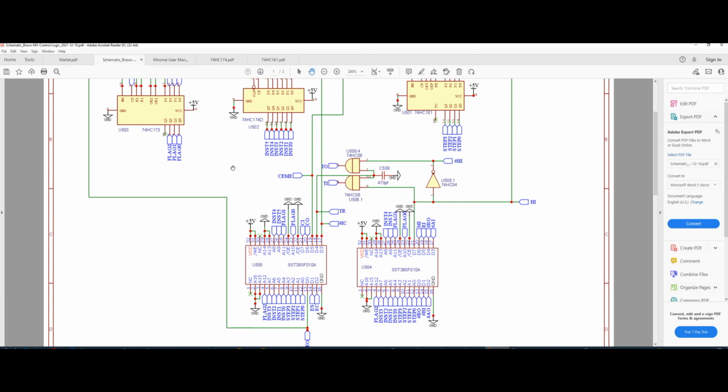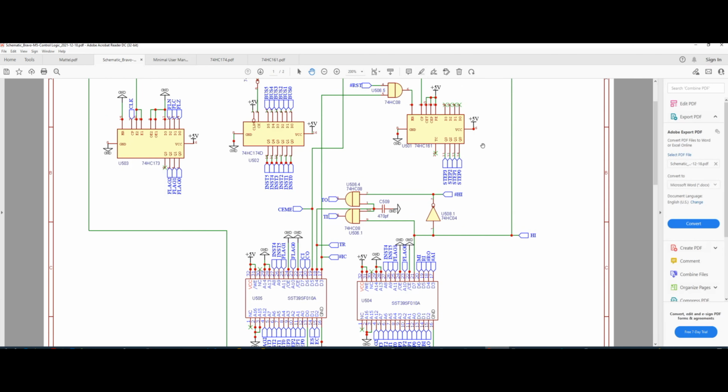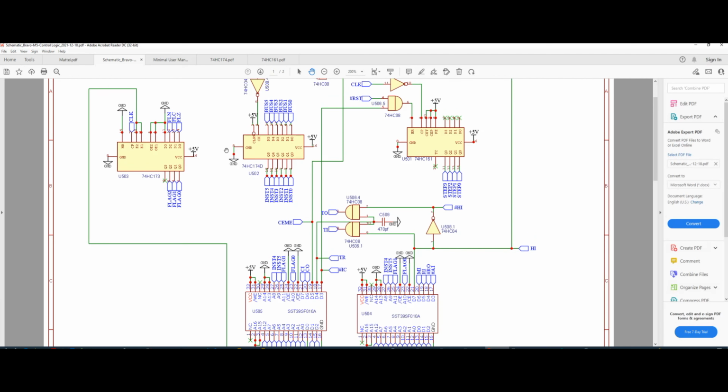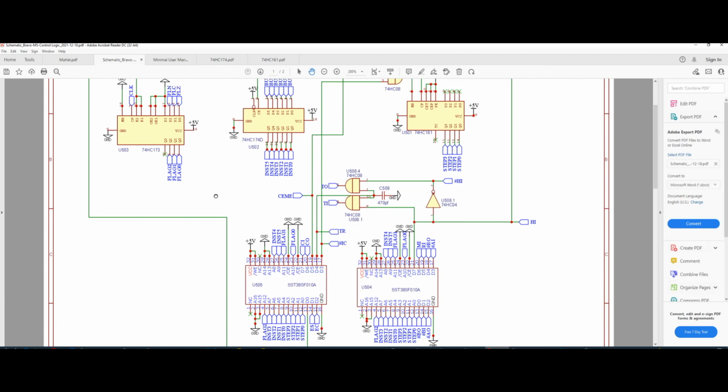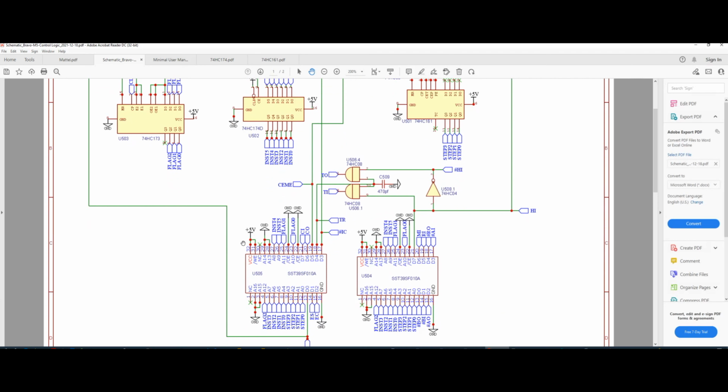However, as I mentioned in the slides, these flash memories are 128 kilobytes, and therefore to address the whole memory you're going to need 17 pins or 17 bits, right? But here we really have only 13 bits that are output of our instruction register part. So we have 4 pins at the end, or 4 most significant bits on both of those chips that are really not doing anything.